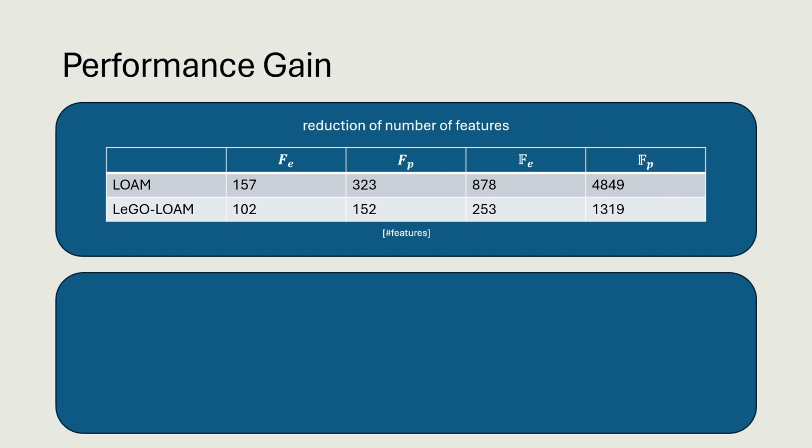The number of iterations until the Levenberg-Marquardt optimization in the LiDAR odometry module converges does not really differ. Indeed, LeGO-LOAM uses the enhanced two-step optimization, but the overall iteration number is comparable to LoAM. The computational time savings in the LiDAR odometry module also come from the reduced number of features. Fewer features to be processed lead to fewer calculations that have to be executed. We obtain a runtime shortening by 34 to 48%.